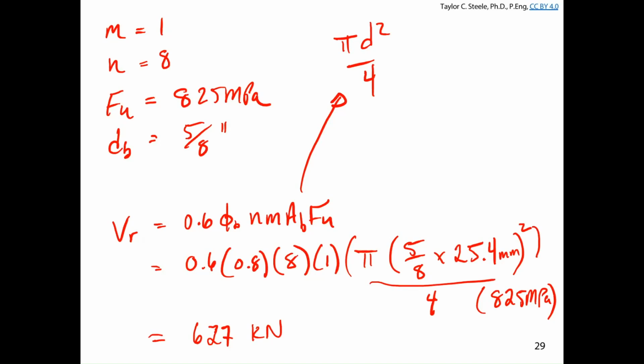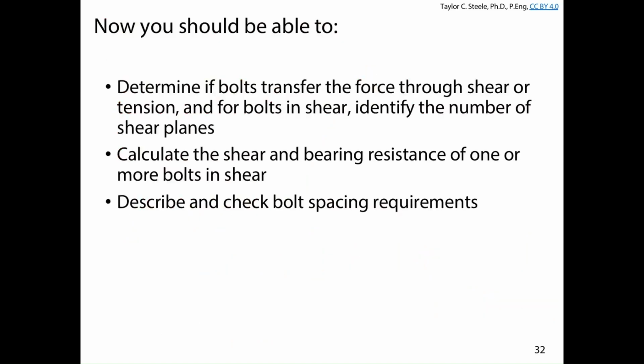Today we talked about bolts in shear and bearing. The most important thing is that you're able to determine whether bolts are carrying tension or shear, and you should be able to identify whether the bolts are in single or double shear. You should be able to calculate the shear and bearing resistance of one or more bolts in here, and describe and check some of the bolting spacing requirements. I've detailed that a little bit in the example notes as well for the example we just went through.